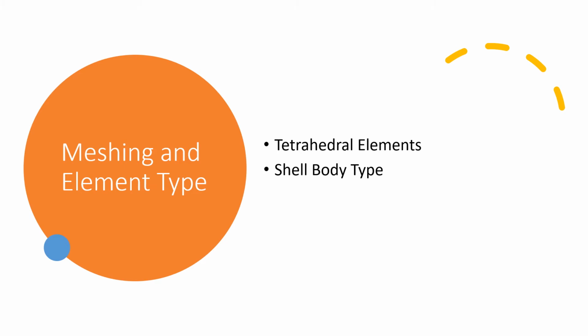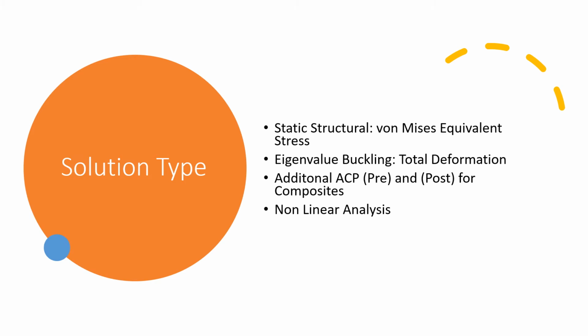Tetrahedral elements were used, as even though they take up a lot of power, they give accurate results, and shell body type was used to reduce the computing time. Additionally, nonlinear analysis was used as it would lead to a more accurate solution.